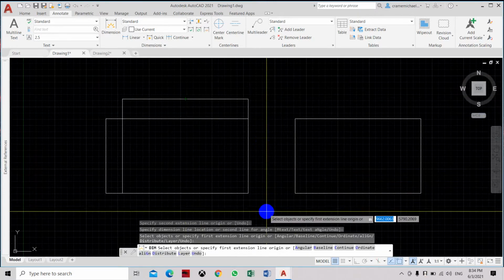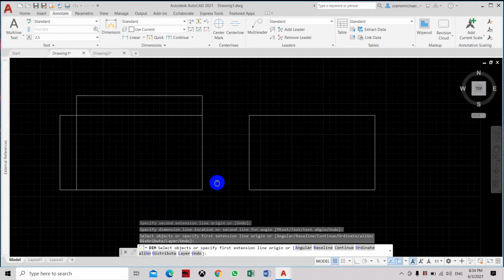Basically, in preparing the dimension style, we need to know the scale of the drawing that we are going to print later on. So we have to establish that, then we can use it to create that scale as reference for the dimension style. Most of the drawings will be scaled 1:100. So let's use 1:100 as an example. So here, I will go to annotate. I will create a new dimension style.